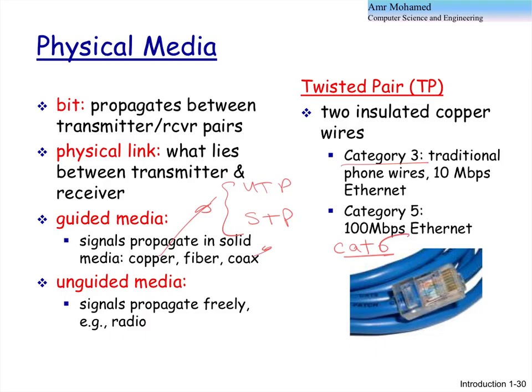Yes. The shielding confines the energy inside the cable. The problem with unshielded twisted pair, because it's unshielded, so the energy dissipates. Okay? So you have certain level of dissipation. So the energy, not the entire energy that you use for transmission, it goes all the way. So the attenuation is faster. The attenuation of the signal